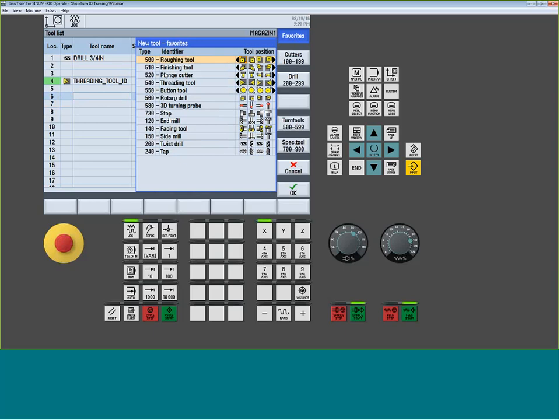So my two most common tool configurations would be either the roughing tool or the finishing tool scenario right here. From there, remember how I said the first position was always OD? And the third is always ID. So if I'm building an ID turning tool for this machine, I'm going to be using this third position for a standard tool that's going to run from the tailstock to the chuck. If I need to back turn, meaning I'm turning from the chuck to the tailstock, then I would use this next position. Yes, we could use neutral as well if I expand over and get to my neutral orientations. But we're using a handed tool, so I'm going to use this first one.